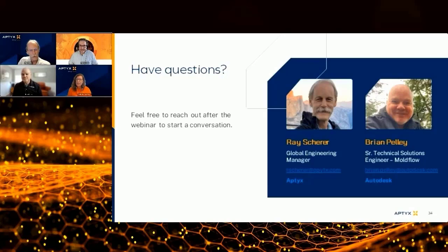I actually got a hold of Brian and was running it by him. At the time, I didn't have Moldflow Insight, but I knew that Insight could go in and predict the warp shape and actually kick out an anti-warp shape. So I thought, if I know I'm going to be wrong, I might as well take a shot at being bad and use that.